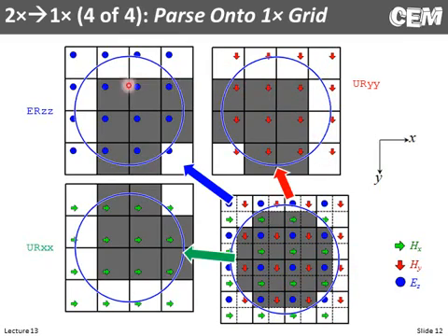But if we go look at that same column for ERZZ, we see it's not inside a material. Here it is, and here it's not. So no material, material, material, no material. So we can very quickly, as you'll see, extract the 3 material arrays that we do want from this single array on the 2x grid.